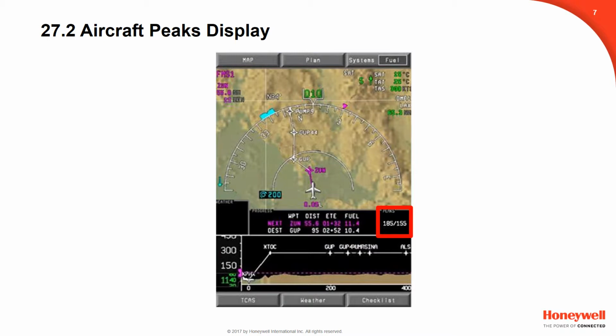A single number displays when the screen is black or blue because the aircraft is over water or flat terrain. Amber dashes appear in the peaks field when the display terrain has overflowed the readout field. There is no readout shown when the valid terrain is not available.